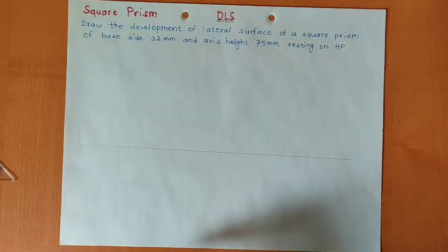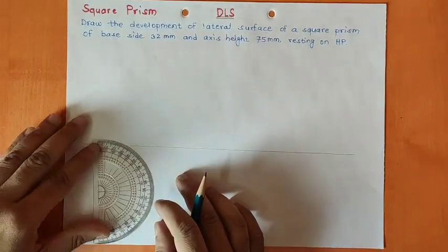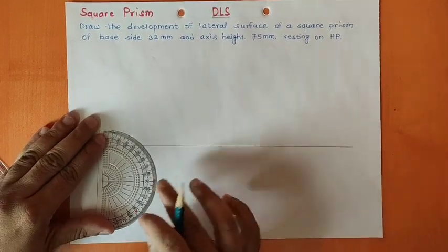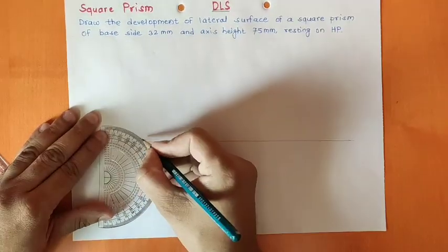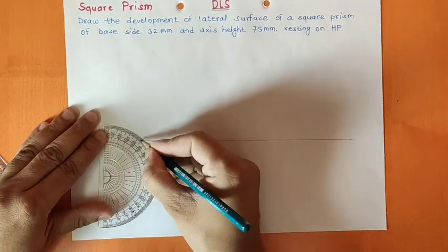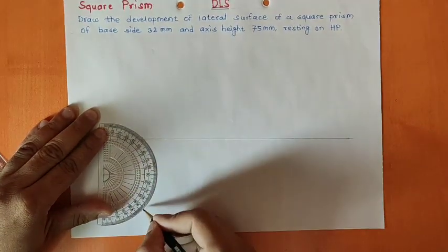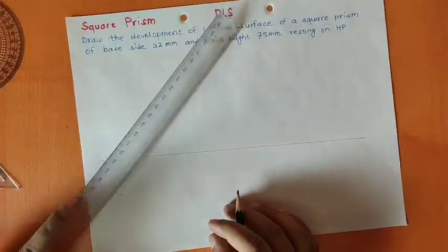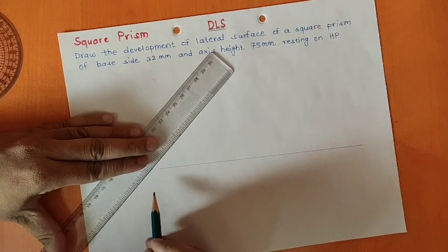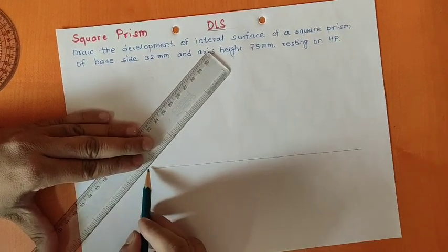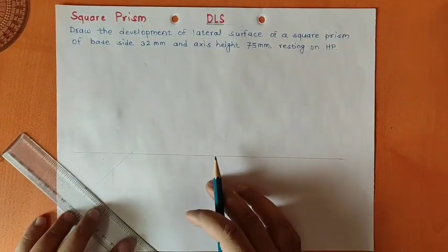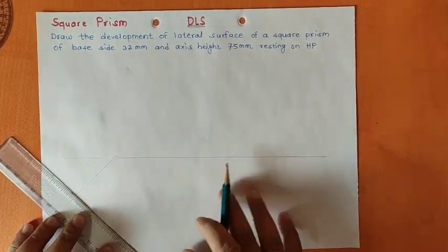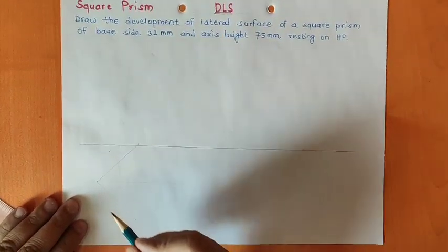So we'll take the angle protractor now. We'll put our angle protractor here accurately, and on both sides of the line, on this side 45 degrees, so 45 is between 40 and 50. Similarly on this side between 40 and 50, 45. So we'll take that distance and we'll draw a thin line on both these sides. As you can see, this total angle is now 90 degrees.